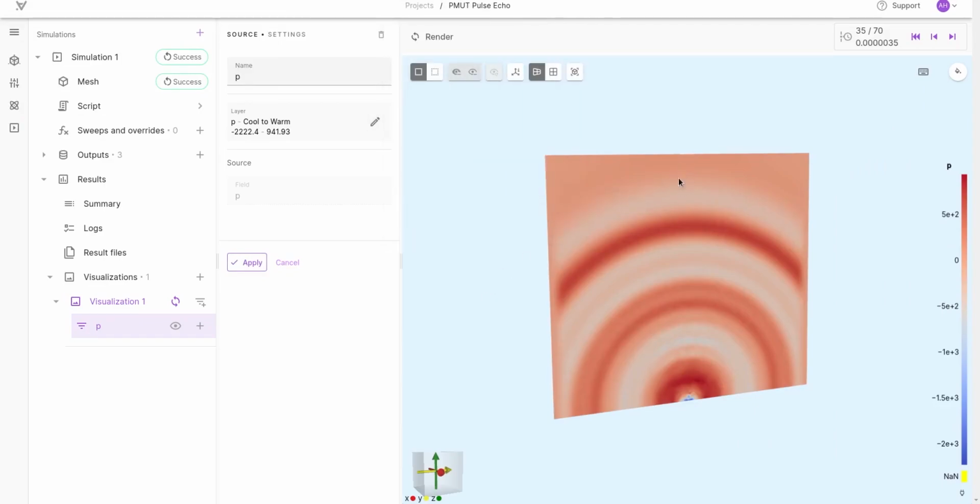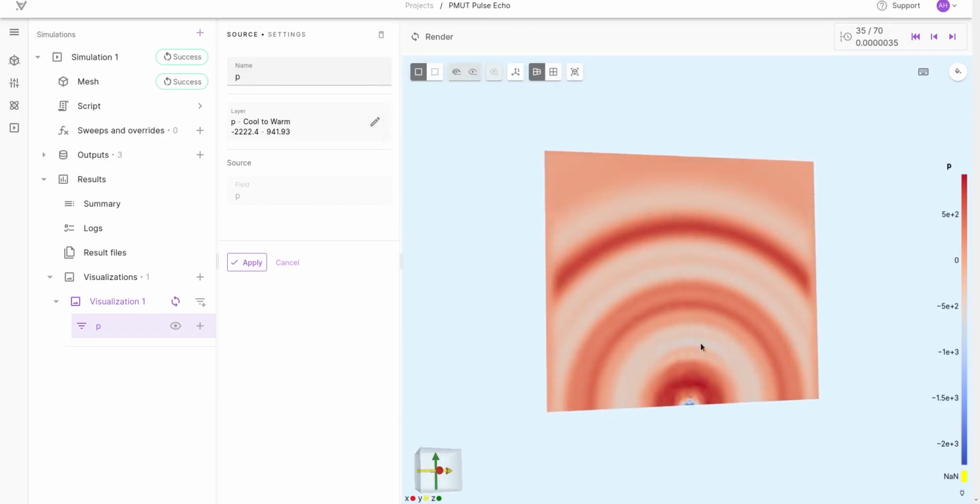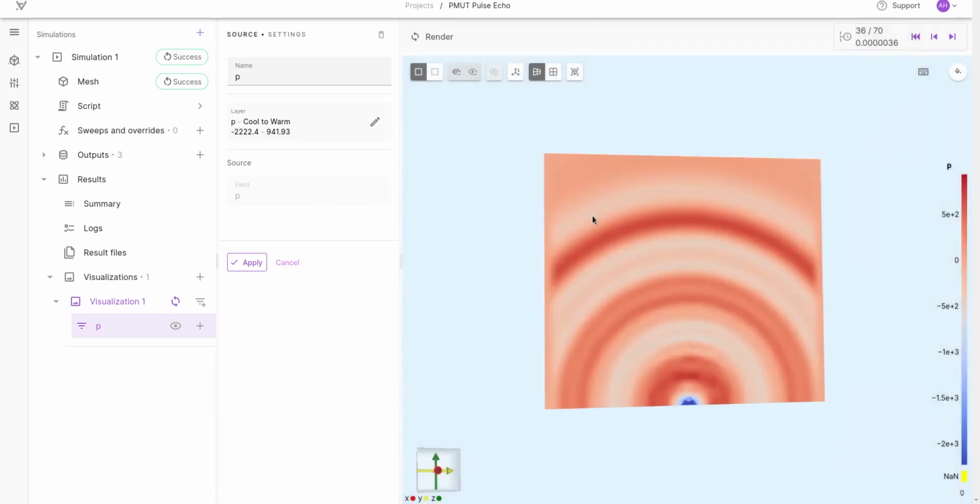The wave starts arriving at the receiver, and you can see that there are extra wavelengths beside the fundamental one, because we actually have excited more than just this 1 megahertz wavelength, because we sent something that resembles more a pulse than a continuous sine wave. Even with a continuous sine wave, because it initially starts from 0, you would also have a bigger harmonic content, but definitely the wave is arriving at the receiver there. And you could go through all the steps to see how this wave propagates.